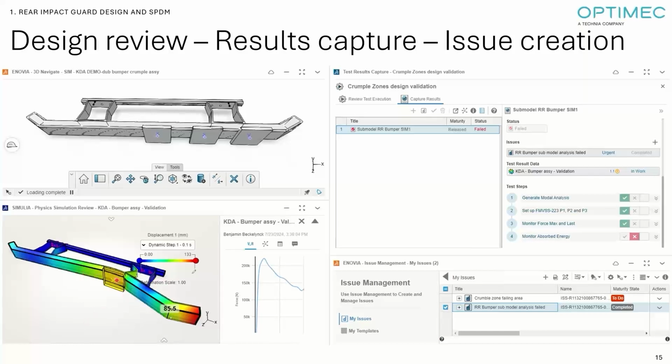Here it's an explicit simulation because you have buckling and post-buckling behavior you want to capture, and a lot of contact between the parts themselves. You can monitor the energy, and what the analysts find out is that with the current design, we will not meet the requirement. Yes, it's stiff enough, but it will not absorb enough energy.